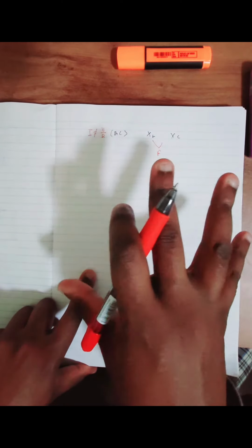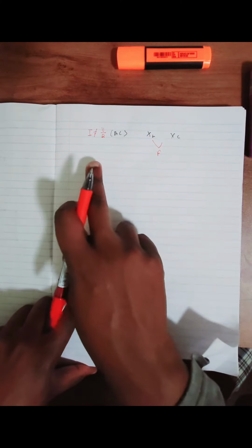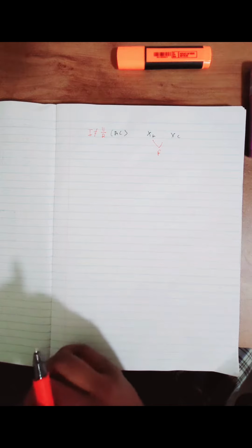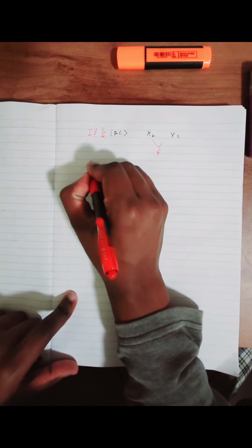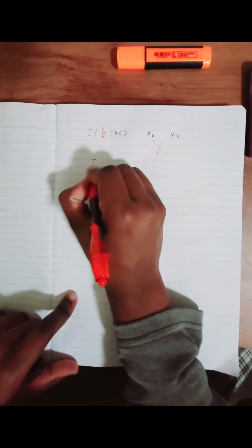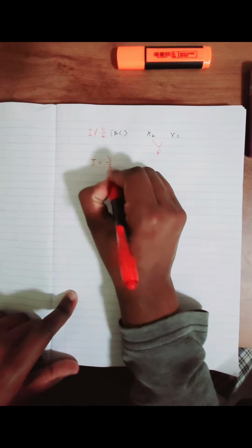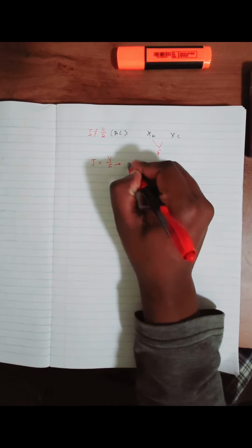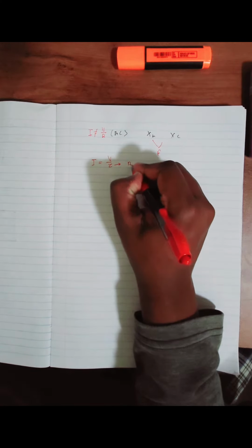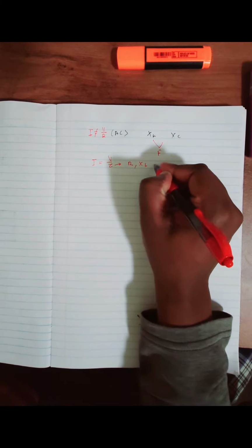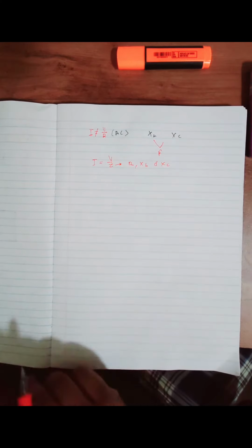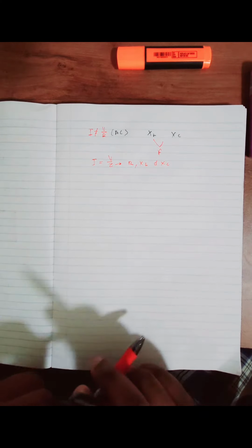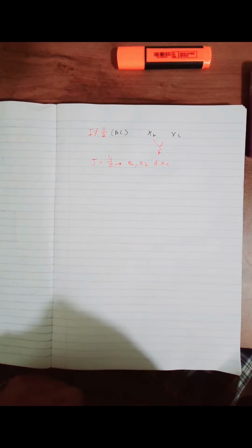I made just a mistake when I was starting the video, so please mind that. So in an AC circuit, guys, Ohm's law is defined as V over the impedance. The impedance takes into account the resistance, the inductive reactance, and the capacitive reactance, because with AC we must take all forms of opposition to the current flow into account.